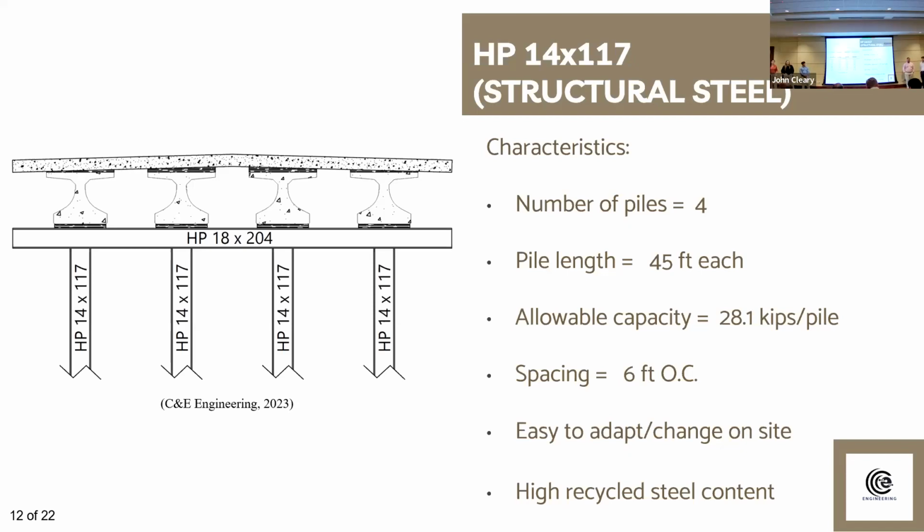On your bridge loading design, I know you mentioned a large tractor several times, but was a particular AASHTO weight class considered? What was the actual loading? I used the LRFD AASHTO design guide, but in meeting with our clients, the loadings they're taking over the bridges and the surrounding areas are higher than that. So I did account for that. They stated that some of the local farmers get their tractors up towards 110 to 120,000 pounds loaded down, way over the maximum requirements. So that was what I used for my design.